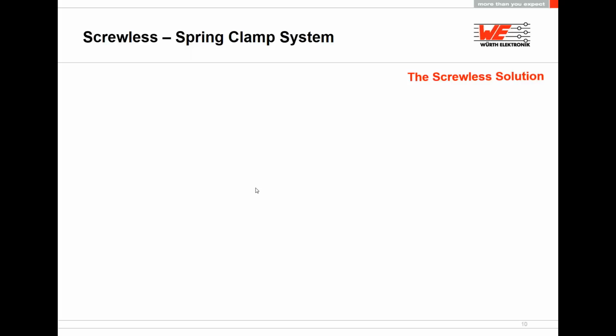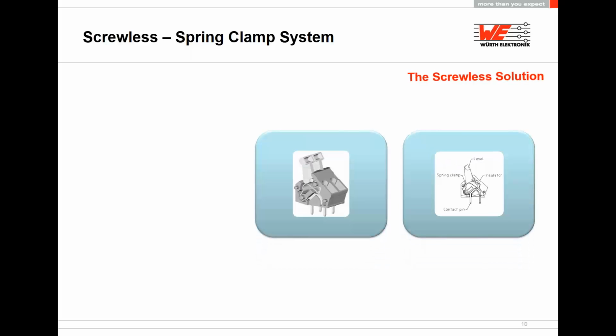Screwless or spring clamp system. As you see here, you push that lever to the back, and here's the hole. You insert the wire. Once you release that lever, it's going to hold the wire tight. It's kind of like a trap.